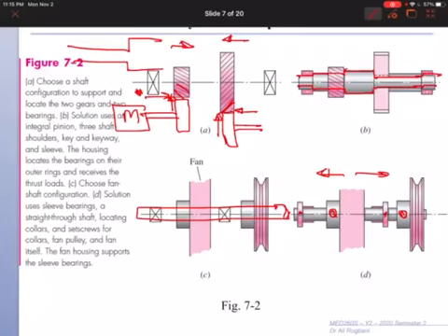This is to support axial forces. To support torsion, we can put keys. The set screws in the bottom example will also provide torsional support for the components. So axial and torsional.